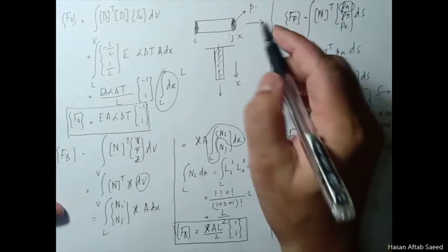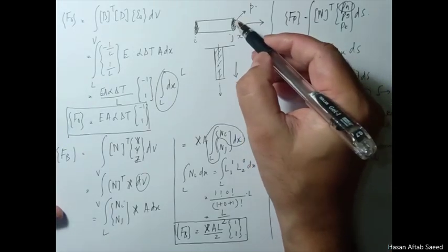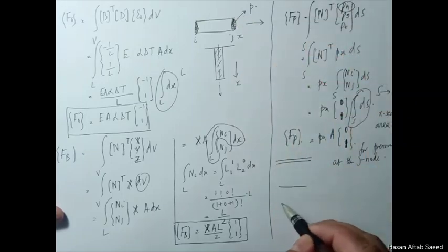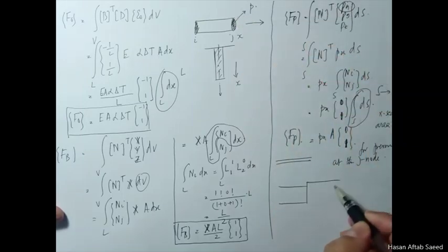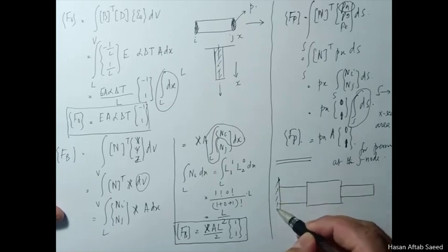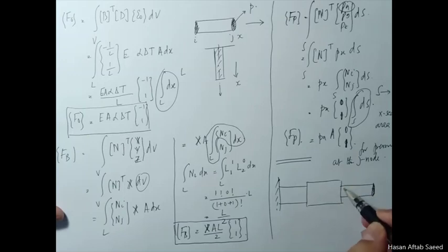It's obvious that this sort of pressure will only occur at the end. For example, if we have this sort of a system, most probably this kind of loading can only occur here, although it can also occur here, and then in that case you will take the area accordingly: outer area of this bigger one minus area of this, because no surface pressure can act on this part.